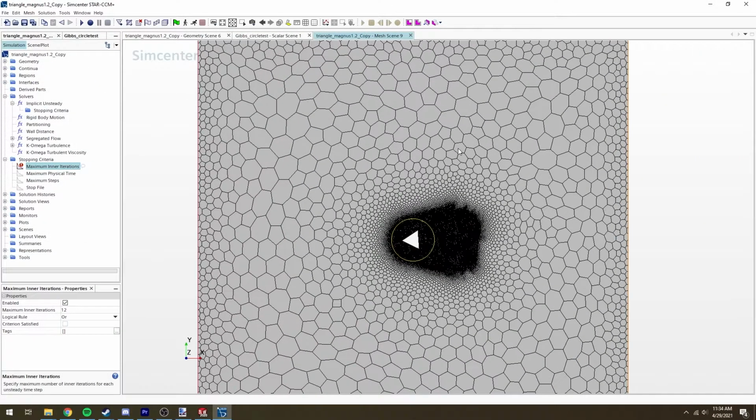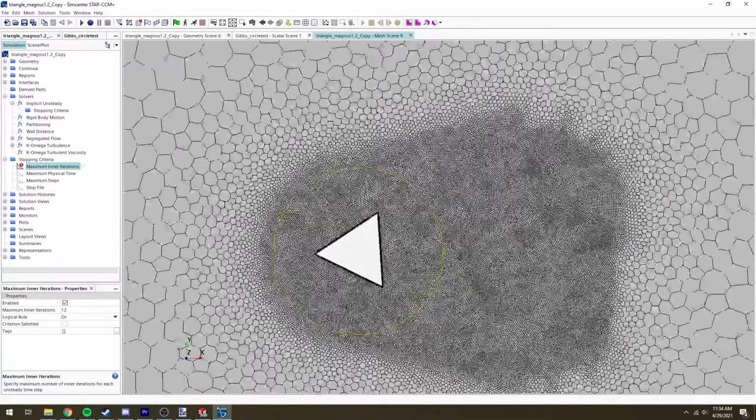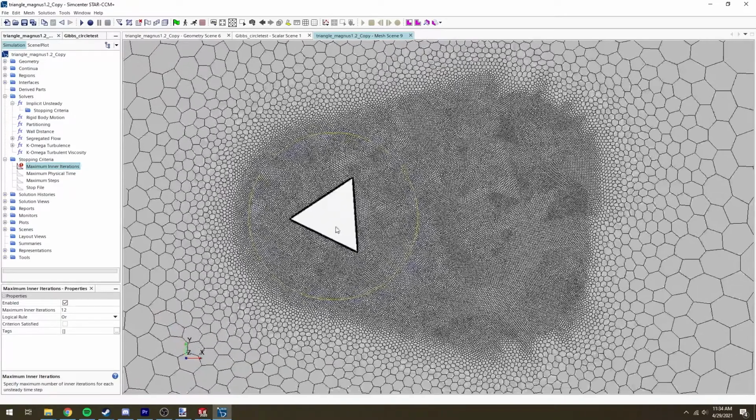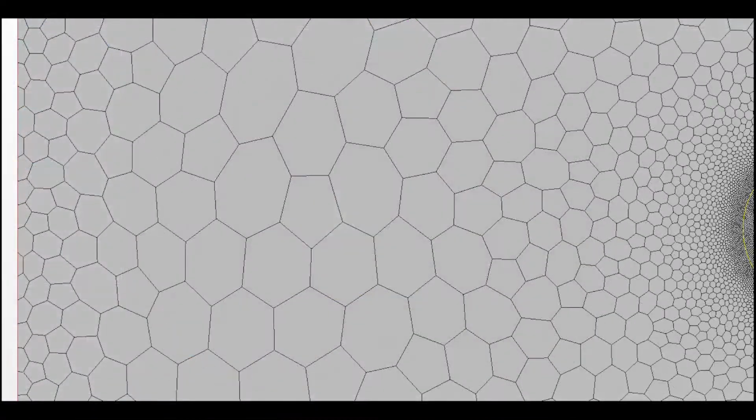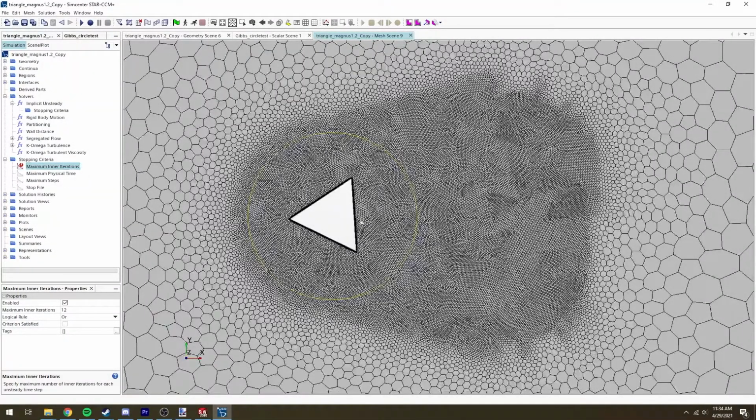For our mesh, we made 2D meshes for each fluid field. We had a base size of 0.01 meters, default surface growth rate of 1.3, and then a boundary relax applied, to reduce the number of elements in the outer sections of the flow field and to create a clear interface between those.